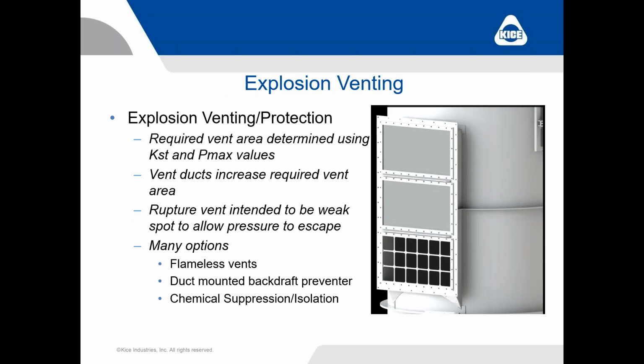Explosion venting, I'm not going to talk about this for very long. This could be another topic for another day and another hour or longer. Explosion venting and explosion protection is becoming more and more important, becoming more and more common. There are lots of things we take into account: KST values, Pmax values of the product and the dust that we're handling. That's what's going to dictate how many vents or how much venting area is required on your filter.